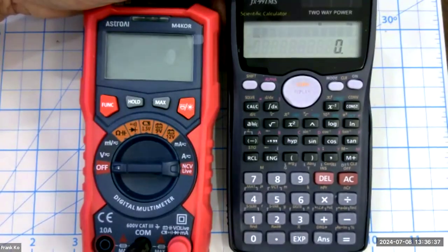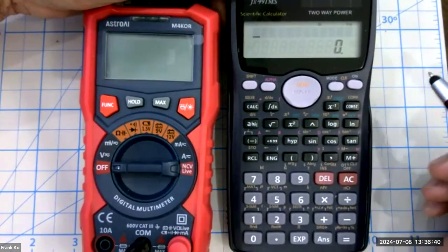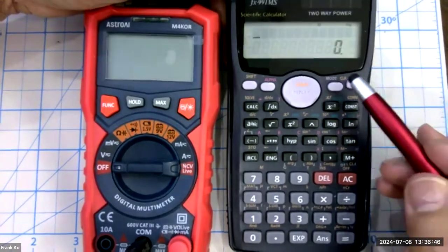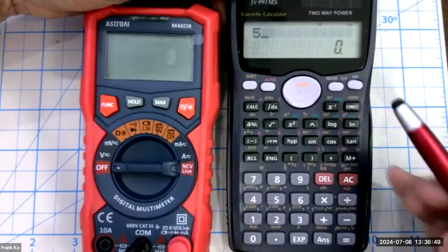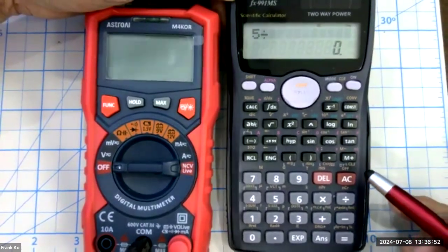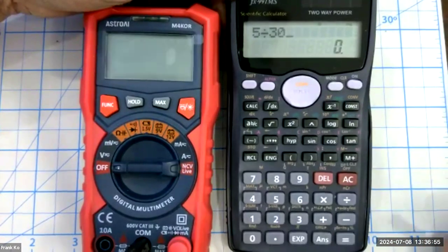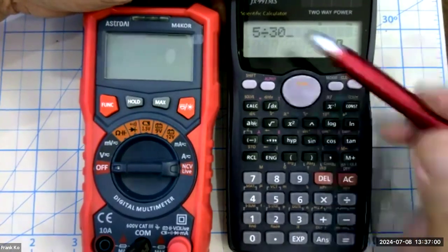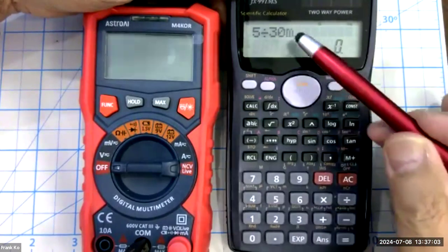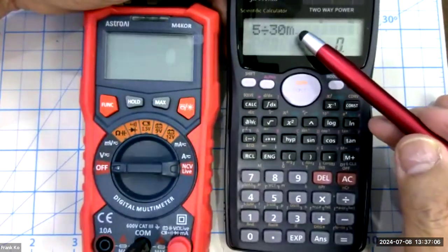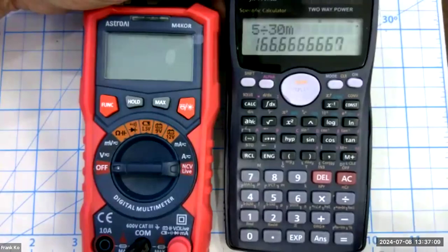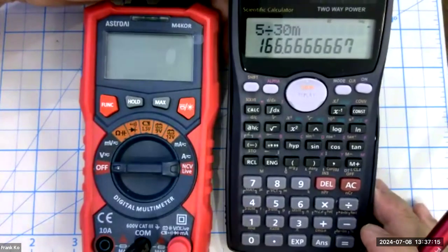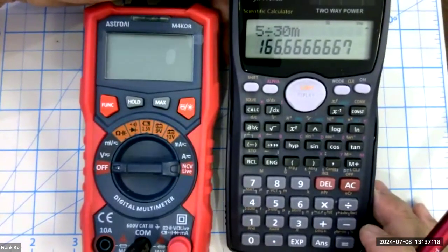Okay, so following Ohm's law, V divided by I. So we take the voltage and we're going to divide by the desired current. So on our calculators, we will simply take 5 and we're going to divide by 30 milli. And on this calculator that would be 30. And milli is this button, second function right above the 5. And so I will hit Shift 5, and I should see the little milli come up on display. So there's my 30 milli, and then I will hit equals. What do I get? 166.67 ohms is our desired ohms.